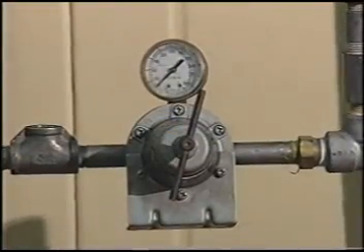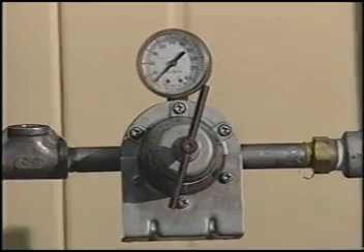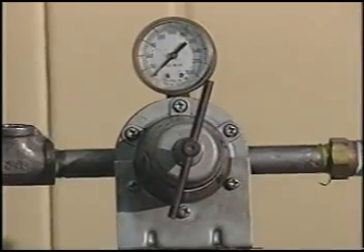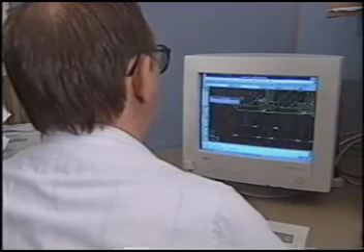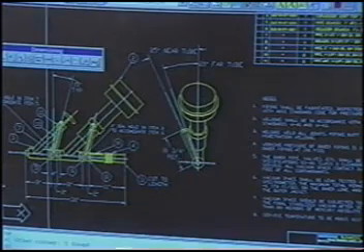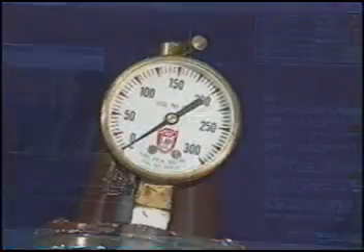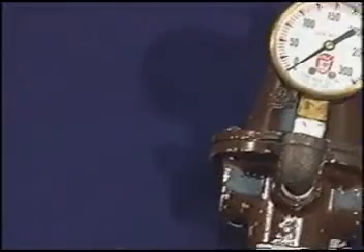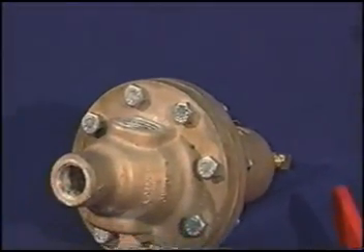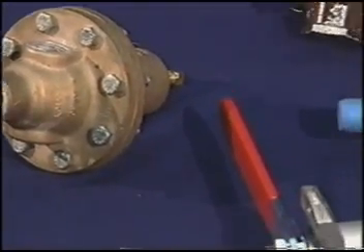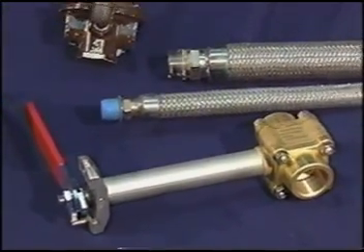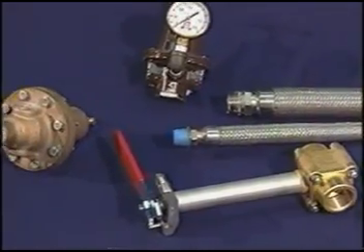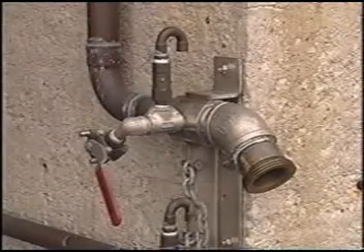You can prevent overpressurization by installing relief valves in any pipe section you can close off that contains liquid or cold gas. Also, design your pipelines to hold the highest possible pressure, so they are rated for maximum working pressure and minimum temperature. This means choosing equipment like regulators, hoses, and liquid transfer lines made only from materials designed specifically for carbon dioxide. Then follow the manufacturer's recommendation for sizing, rating, and application.